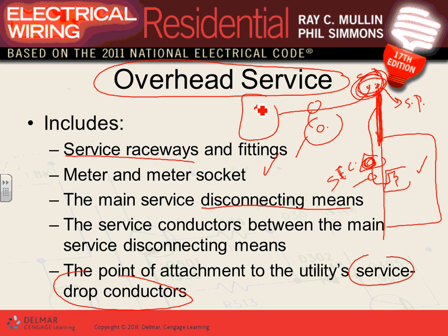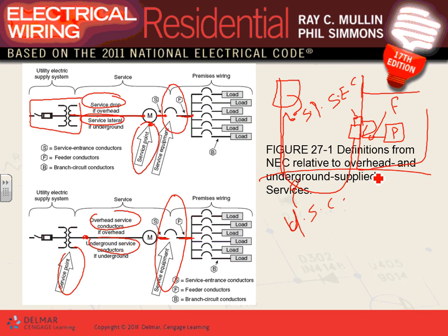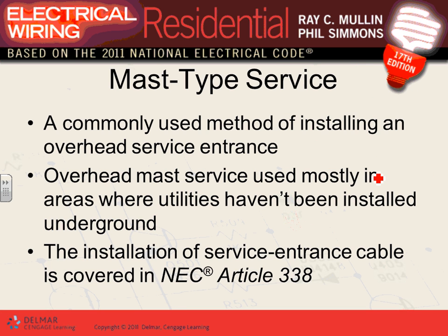So these are the questions they're going to ask: where is the service point? You're going to ask yourself, where's the service point? I need to talk to the utilities. Is the service point right here, or is it right here? And you're going to see, guys, service point for residential is typically right at the top of the mast, a lot of them. Or when you go to the project that we're using, we're going underground, and the service point is going to be right at the meter. And we're going to assume right at the pole. We'll show you when we reach it.